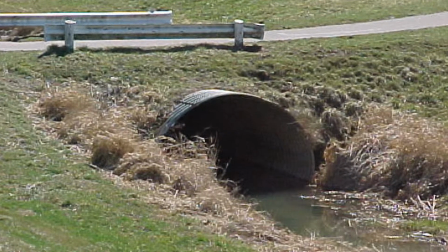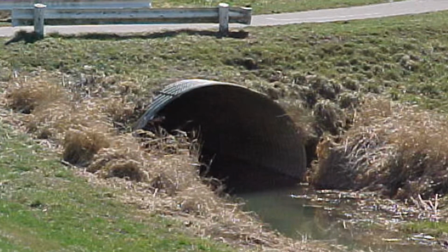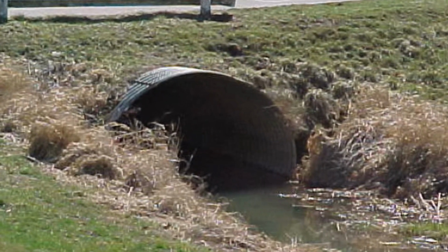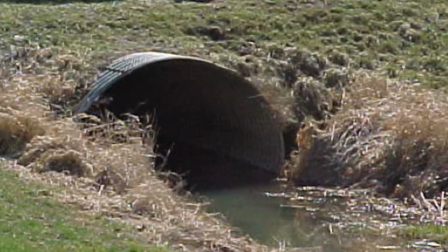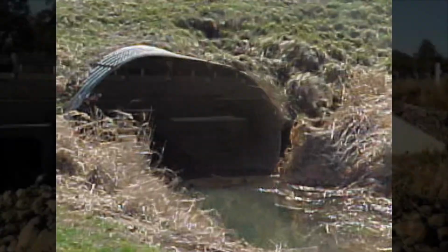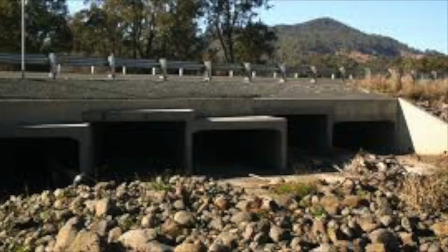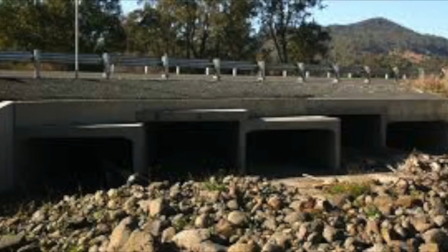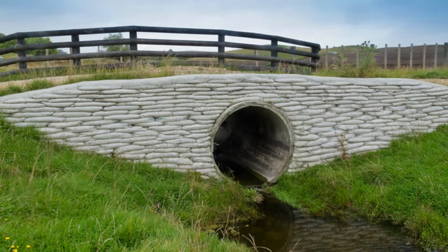A culvert is a tunnel structure embedded under a roadway or railways to provide cross drainage or convey water to the other side of the embankment. Common usages of culverts include cross drains and passing water under a road at natural drainage and stream crossings, in floodways to enable low-intensity floodwaters to be discharged without any overtopping, in areas where construction of bridges is not viable due to cost versus benefit.